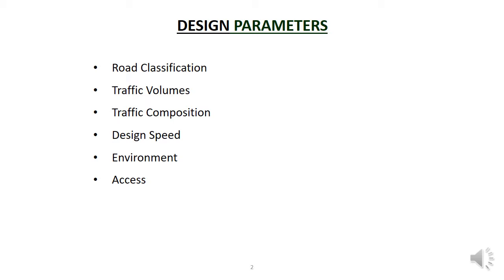The speed that the traffic moves influences the design in several ways. Fast-moving traffic exerts more load on the road, especially when turning, braking, and accelerating. Additionally, the bends on the road need to be designed to allow cars to travel around them at the design speed. On faster roads, this means that drivers need to be able to slowly ease into the turn rather than having to throw the car into a full turn immediately upon entering the bend.